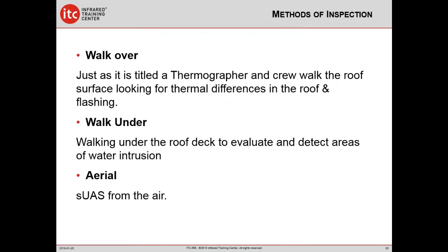make sure what's going on under that membrane. Walk under. This is where you have access to the underside of the roof. And of course, what you're looking for here is a cooler thermal anomaly where water is presenting itself through the membrane, and then aerial.